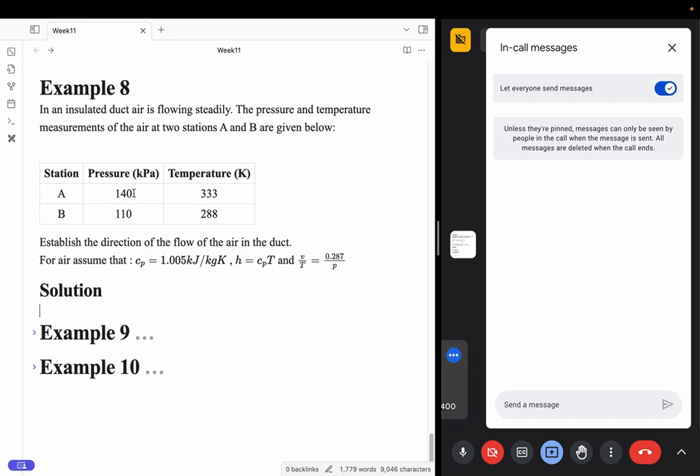So why is the pressure decreasing and temperature decreasing? For example, if you consider an adiabatic process, it is either adiabatic expansion or compression. Let's say adiabatic compression. So what would happen to pressure and temperature in an adiabatic compression process? In adiabatic compression, your pressure will increase and temperature also increases, right? In adiabatic expansion, it will be just the opposite. Your pressure decreases and your temperature decreases, like when you're pumping your car tire or whatever it is.